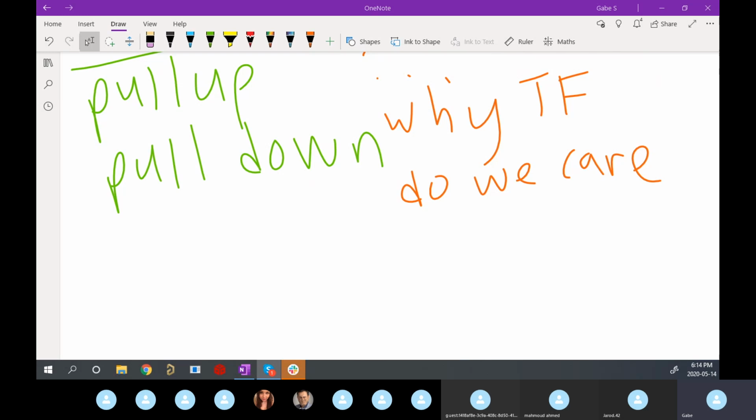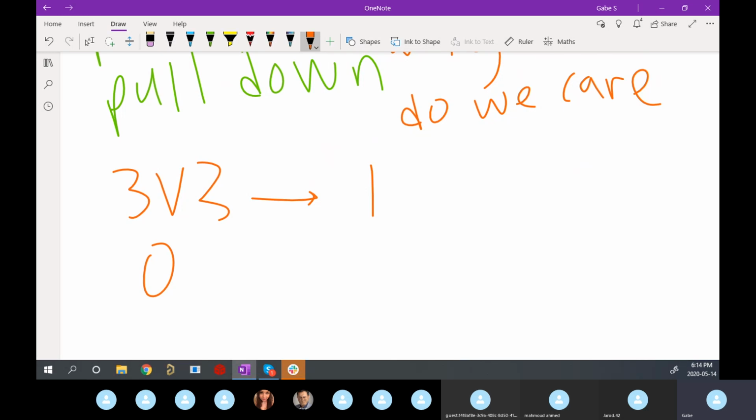Yeah, that's exactly right. We want to make sure that our input pin always has a defined state, right? We want it to be either a 0 or 1, and we know that it's not floating to something random. Just a reminder that the way a microcontroller interprets a 0 or 1 is based on its logic level. So if I have a 3.3 volt logic level microcontroller, a 1 would be 3v3 into it, right? And then 0 volts is logic 0, which is easy.